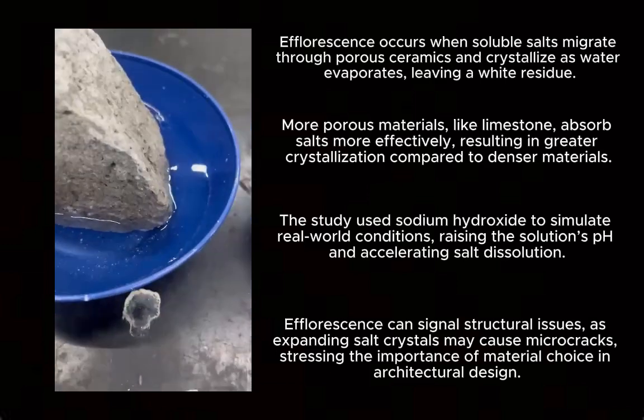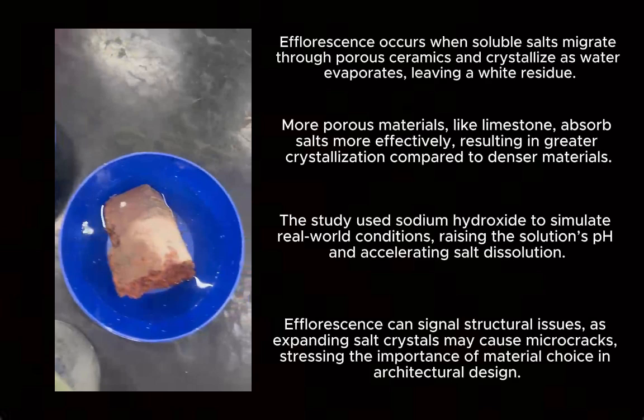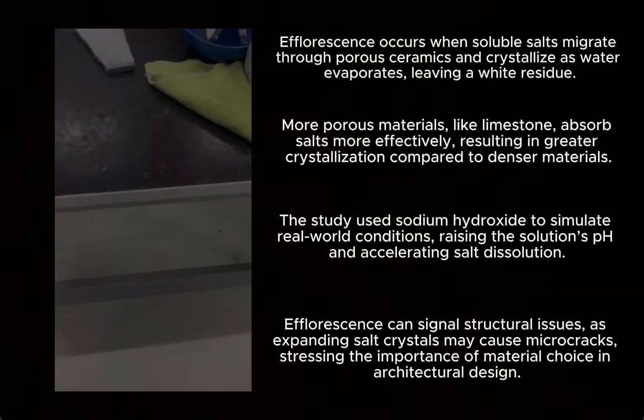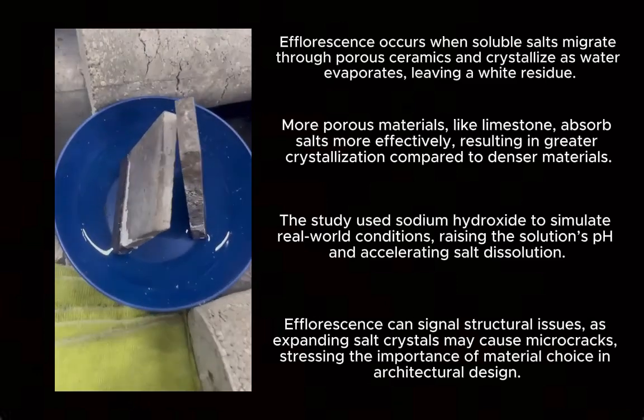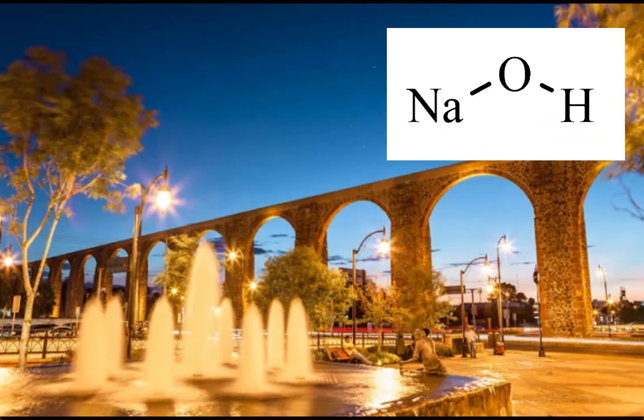More porous materials like limestone absorbed salts more effectively, leading to greater crystallization, while denser tiles showed minimal effects. This suggests that higher porosity enhances salt migration and exacerbates efflorescence. We simulated real-world conditions using sodium hydroxide, which raised the solution's pH and accelerated salt dissolution.